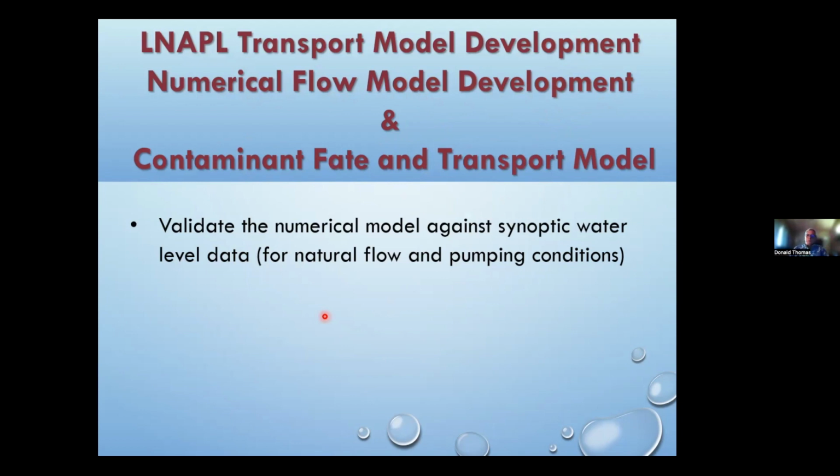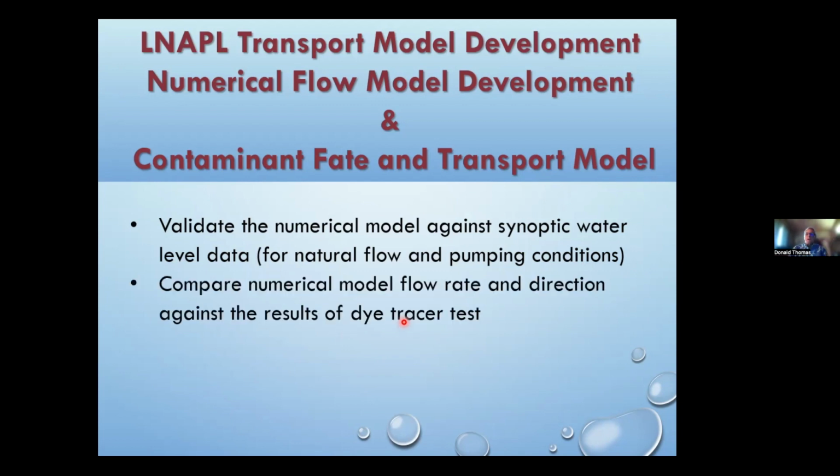Once we develop the models, we then validate those models using measured water levels over extended period of time for natural flow conditions as well as under pumping conditions. And then with that, we should be able to make much better estimates of groundwater flow within this region, compare those against also the dye tracer test, and come up with the best possible model we can.